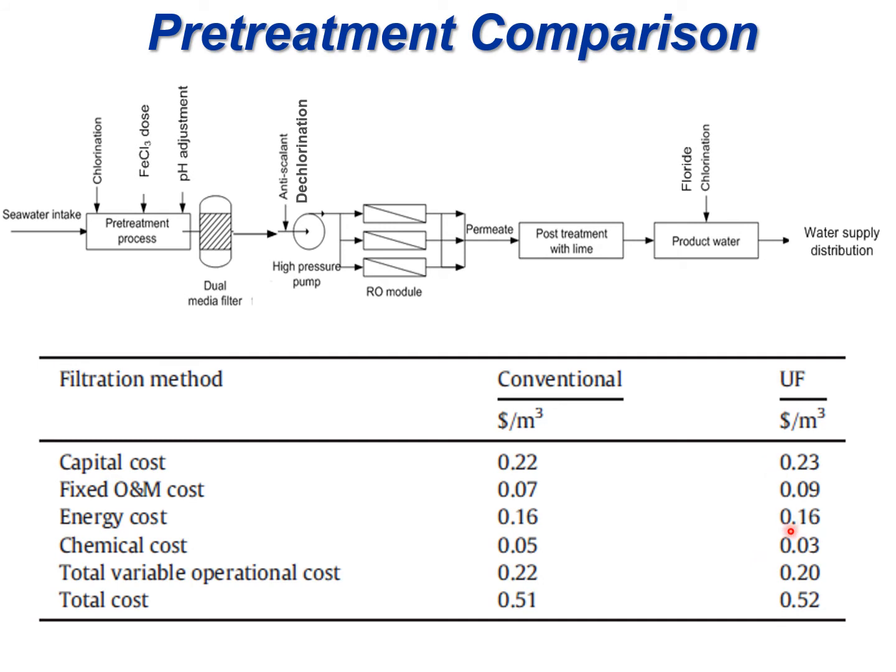And Southern Desalination Plant and Adelaide Desalination Plant include ultrafiltration pretreatment. So 2 plants consist of ultrafiltration, advanced pretreatment, and 4 plants are conventional pretreatment. When you consider the capital cost, operation and maintenance cost, and energy cost, the total cost is very similar, but people believe ultrafiltration, advanced pretreatment gives better quality of pretreated water and very consistent performance of reverse osmosis. That's why people like to have more ultrafiltration pretreatment.